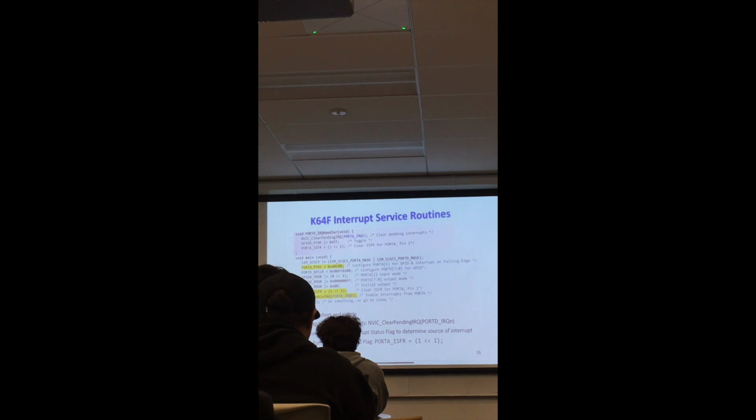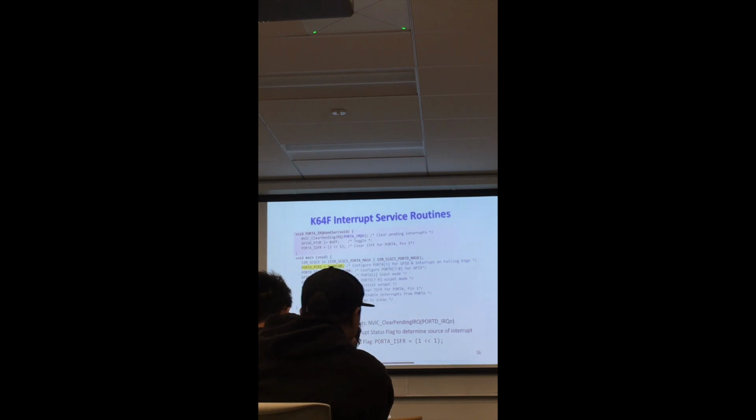Because it may be part of the system implementation that you disable interrupts, then enable them, and then want to reconfigure interrupts while it is still running. In this case, when you reconfigure interrupts, make sure that you disable them for all interrupts, because it will create a mess.